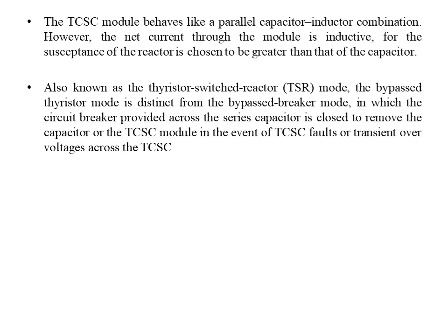Also known as thyristor switched reactor mode (TSR), the bypass thyristor mode is distinct from bypass breaker mode, in which the circuit breaker provided across the series capacitor is closed to remove the capacitor or TCSC module in the event of TCSC faults or transient overvoltage across the TCSC.